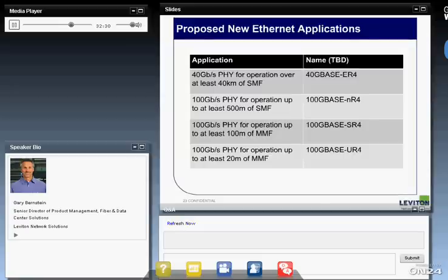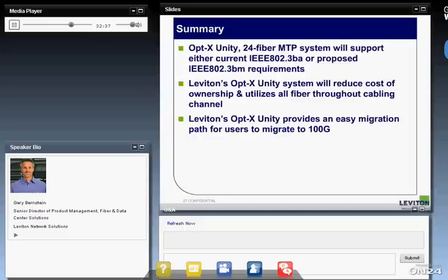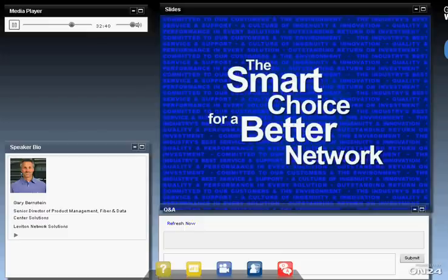And then we have a couple other questions I want to throw in here. What's the price delta from a multi-mode to single-mode 100G transceiver? Do you know what that might be? Yeah, I've looked at it. Just in the market, there is some variation. That's why the reality is a lot of people are going towards the multi-mode route right now. On the 100 gig side, it's probably about 30 times more for a single mode LR4 versus a multi-mode transceiver. Just the transceiver we're talking about. The 40 gig, as a reference point, doesn't have as big of a delta, and that one is probably closer to eight times for single mode. Okay.